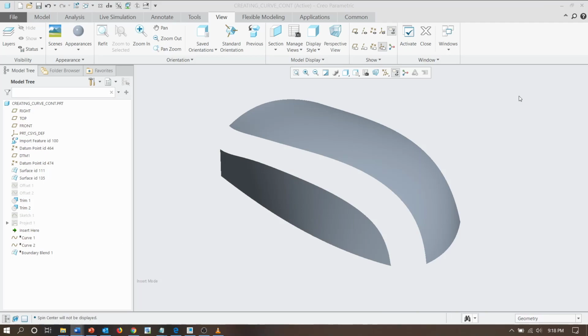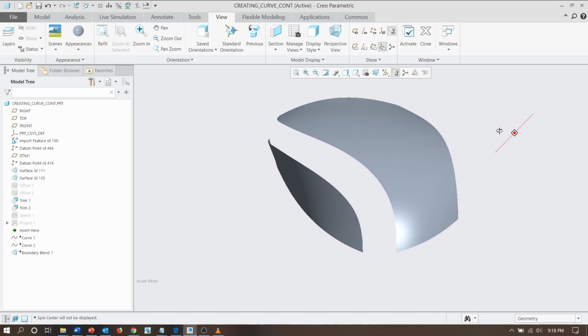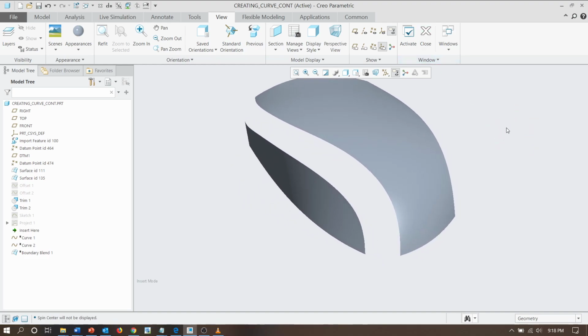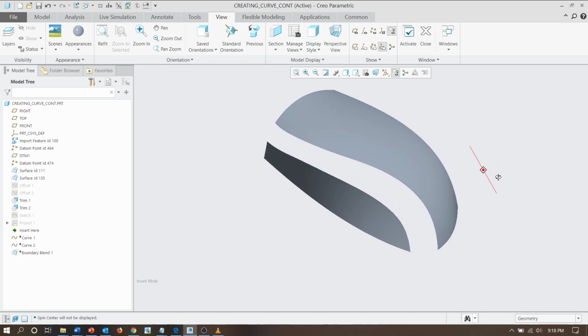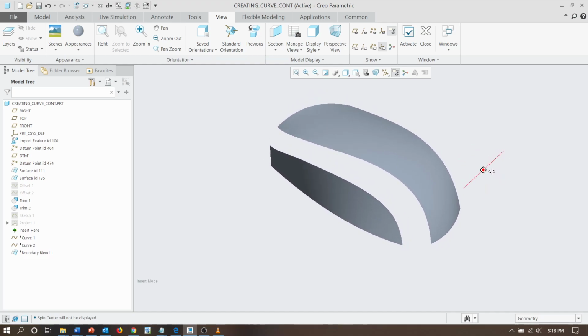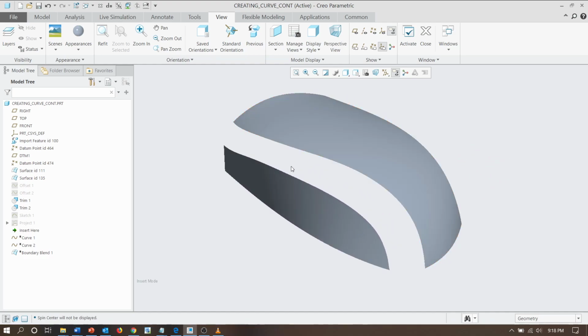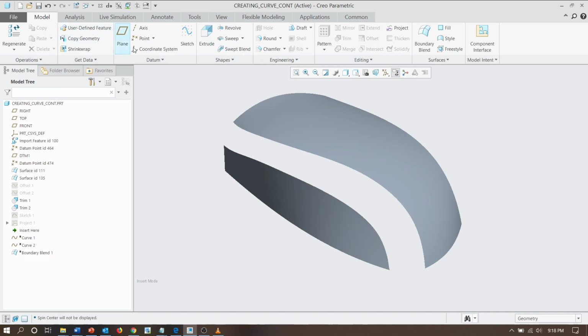So I'll go ahead and jump into the demonstration. I'll be using Creo 5.0 to conduct the example. And we'll start by looking at the beginnings of a surface for a mouse, right? Such as the one we saw on the first slide. And what I'll do is I'll use a boundary blend to create a surface that links this top portion with the one on the side. So let's go ahead and do that.